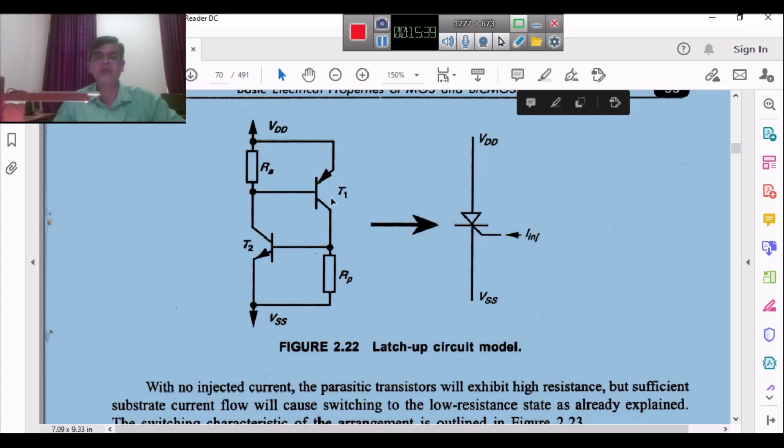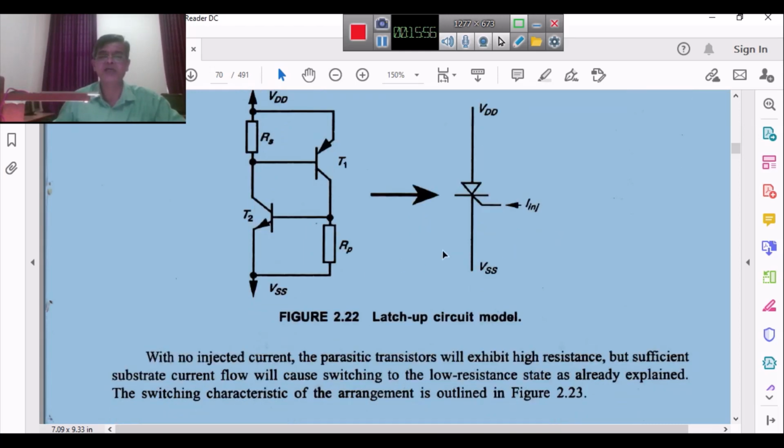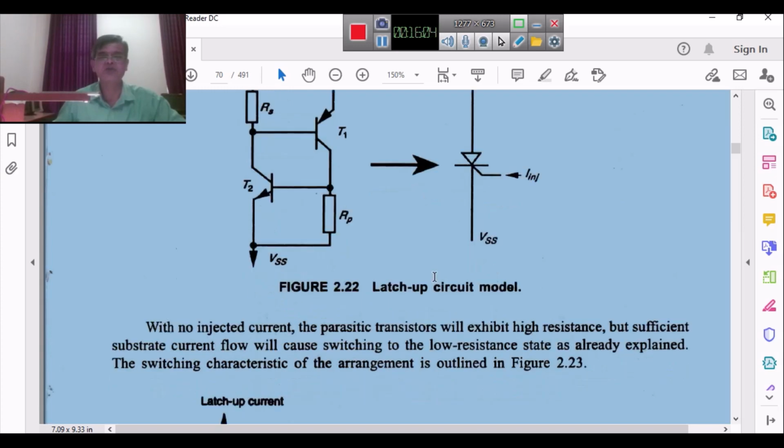What happens? Then it may result in the spoiling of the transistor. That means current gets latched. That is called latchup in CMOS. Because of the latchup, what happens? Transistor action fails. CMOS will never work as CMOS now. Okay, this is a disastrous result. That is what we say: low conducting paths are created due to the parasitics between the power rails VDD and VSS. Okay, I think you understood this.